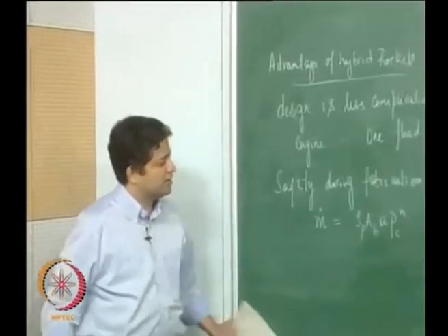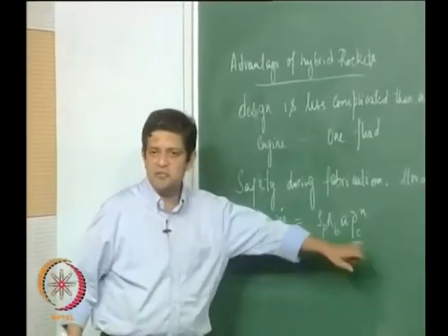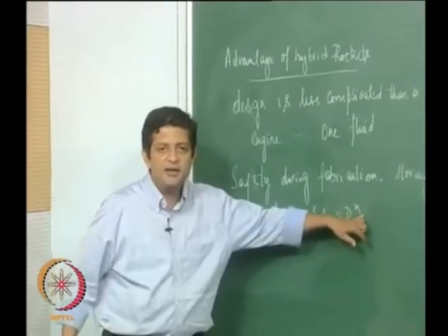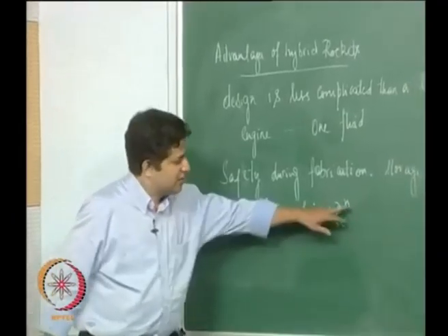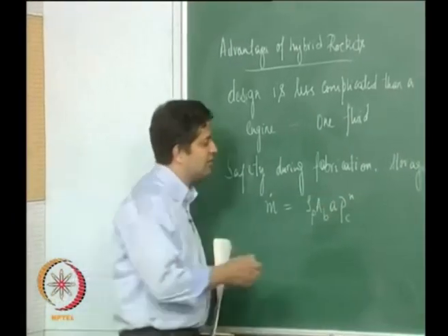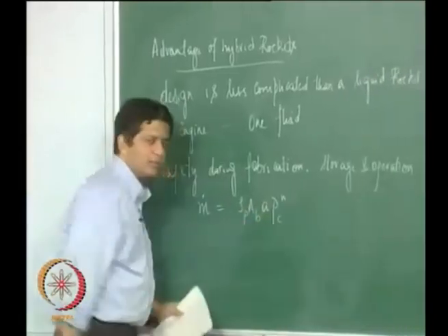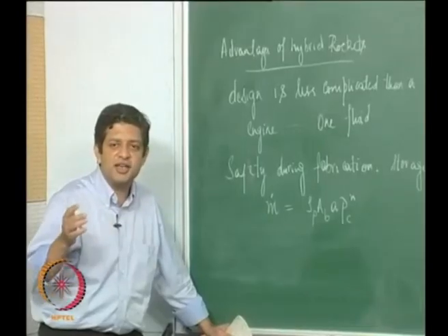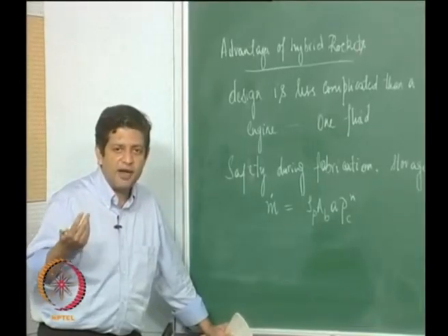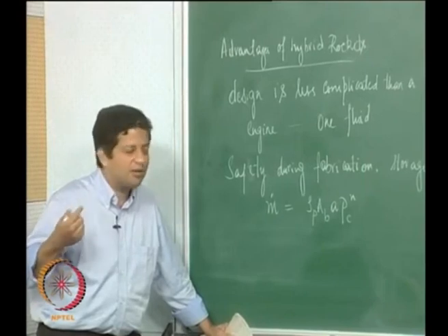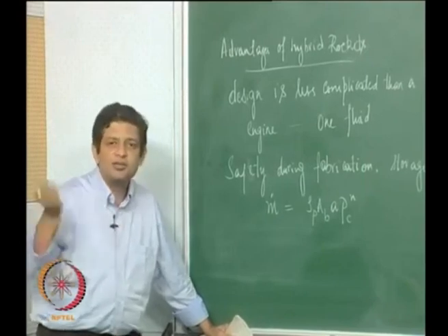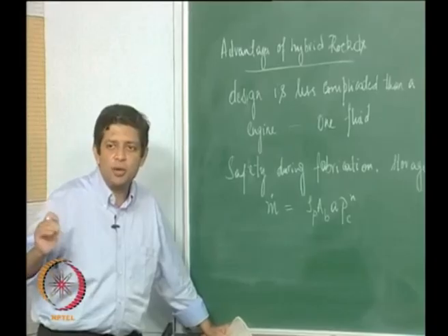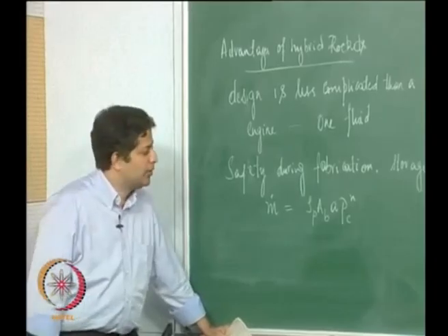So it is sensitive to the pressure, as I had already said, and we had discussed this, that if n is high, the chances of explosion are much larger because the pressure gets amplified due to, if there are changes to the burning surface area or other parameters, then the pressure gets amplified because PC goes as 1 by 1 minus n. So therefore